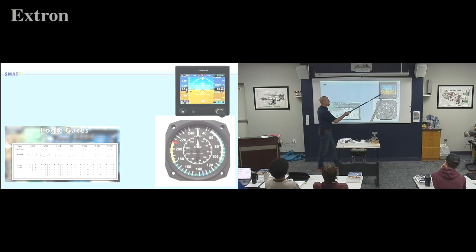Now if we go up to this one, he's got an airspeed indicator over here with some numbers. Ultimately, we're going to have a sensor that senses what the air pressure is, that's going to convert it to a digital signal. But that digital signal is just going to be a bunch of zeros and a bunch of ones, coming across like 0111, 0011, 0111. And somewhere along the line, there's going to be a computer processor that has to not only convert the signal, but then also take that signal back and say, okay, that tiny little pixel, do I want that to be on or off? Do I want it to be white or black? What about the one next to it, right?